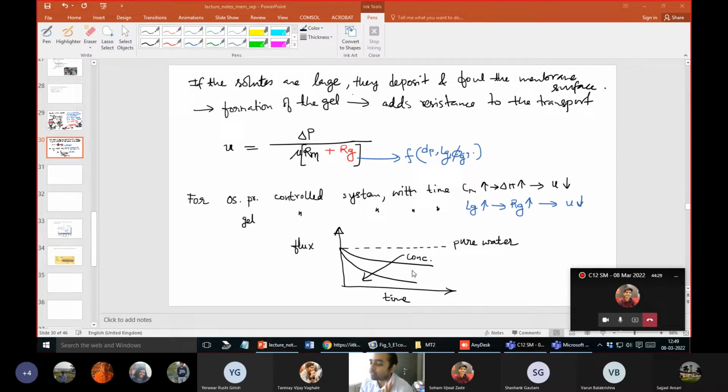So one thing is, of course, the flow. If you increase the strength of your flow or the Reynolds number, in the case of this cross flow or transverse flow action, that would reduce the impact of the fouling. Some other methods, even with flow, could also be done. For example, pulsating flow.